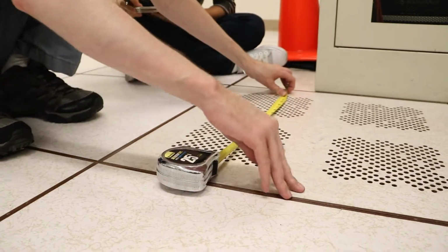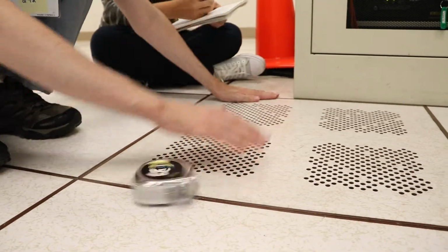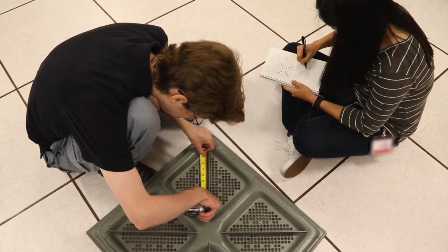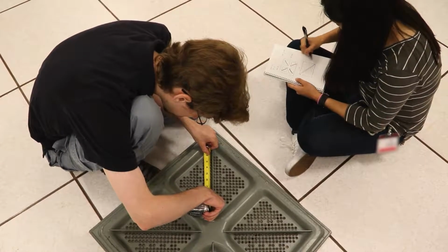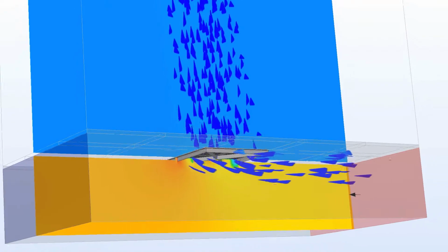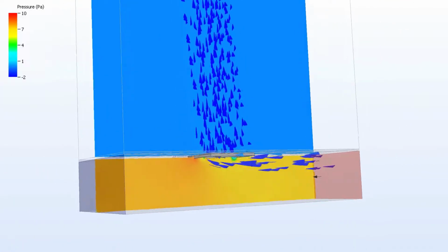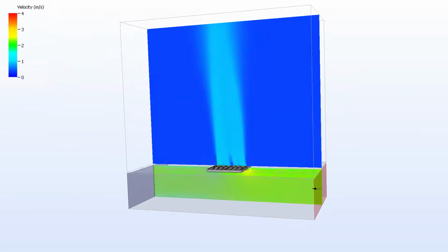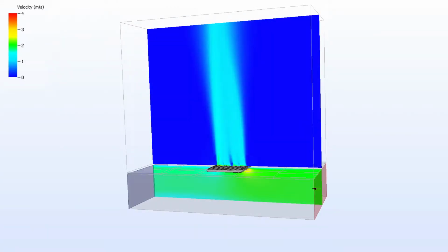Air leakage around the perimeter is mapped, accounting for semi-sealed piping cutouts or holes in the raised floor. Next, we survey the cabinet and grill layout, accounting for details such as placement and type. Details of grills or cabinets may be recorded for the model if the objects do not already exist in our library. The objects will be simplified later using a flow simulation to make sure all important characteristics are captured.